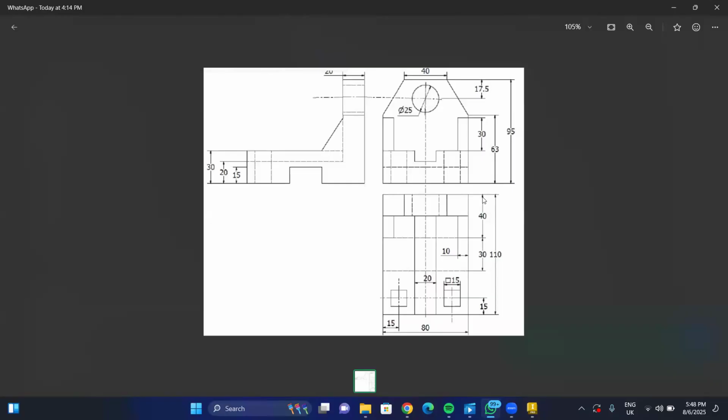And this diagram is showing me where that web is located. Actually, from here to here is 40, or from here, that groove is 30. The height of that is 30. And the thickness of this, I think that thickness is given as 10. So that's what I want to create on that block now, and I will extrude.